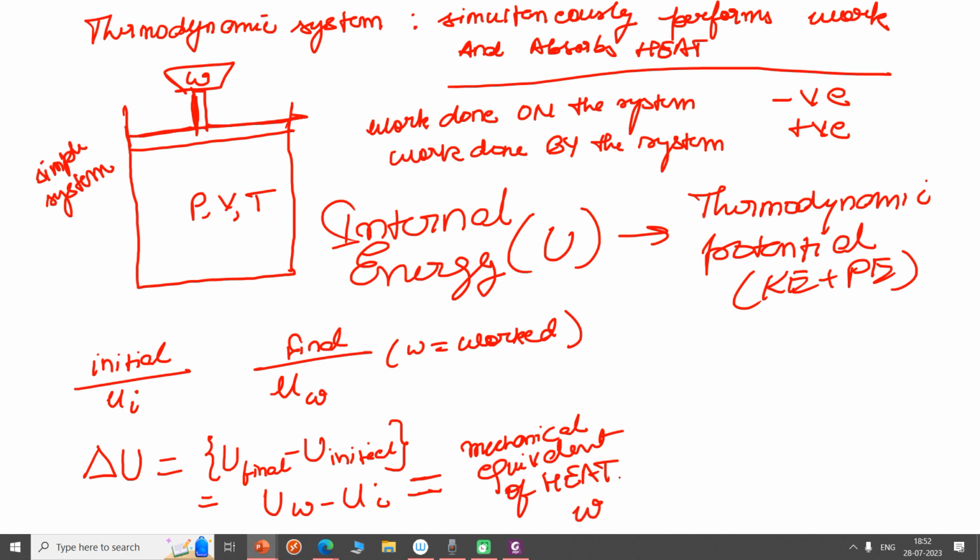And this W is my mechanical work, and that is represented by P dV. It's easy to see if we have, let's say, a difference in volume, for work done at a constant pressure, the difference in the volume times the pressure will give us the work done.